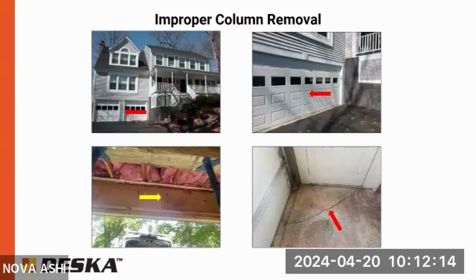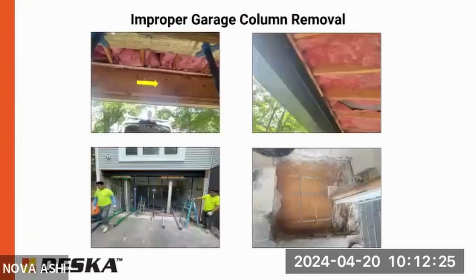So essentially you replace the wood beam with a steel beam? Exactly. But also reinforce those. Yep. So this picture down here with the crack, at the bottom right, concrete was removed. We doweled in some steel reinforcement into the existing footings and then poured a larger footing to compensate for the additional load.